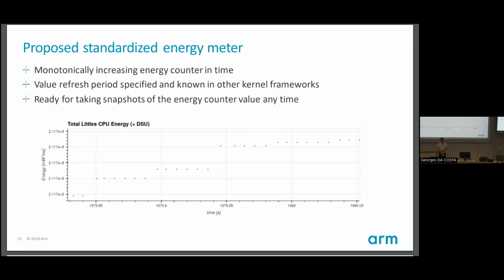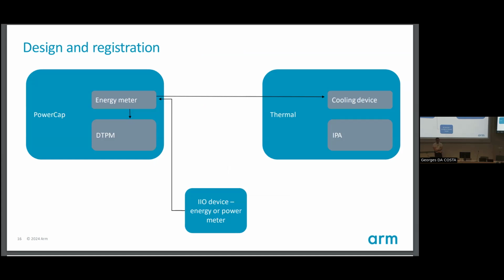Okay, thanks, Yuri. Just one question. Have you measured how much energy you're consuming to measure the energy? Well, it's a problem of how much waste is in your PMIC, because the efficiency of the PMIC is not 100%. So you drop some energy there in order to make a new voltage for your CPU in the DVFS. No, I mean not only at the PMIC level, but my understanding is that you have a thread waking up regularly to monitor that. So you have one CPU waking up and running to monitor. Have you estimated what kind of noise that is?